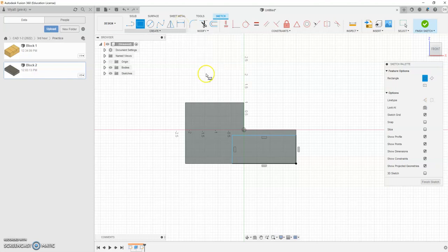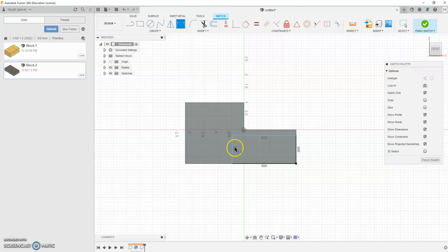All right, so now these 2 lines are constrained. They're fully black, just as they should be. I'm going to come in here to my sketch dimension and dimension the width of this. Again, this was 2, and I think this was 2 here. So I'm going to make this top one 2 1/4, just a 1/4 inch over. Whoops, I don't know what I just did. Oh, there we go. Computer was just lagging.